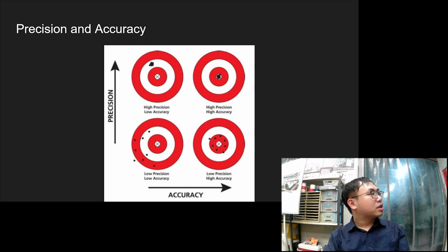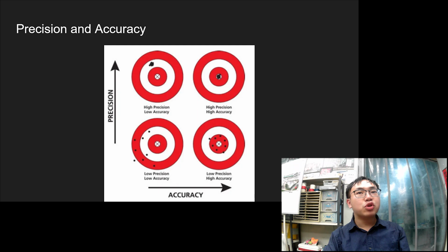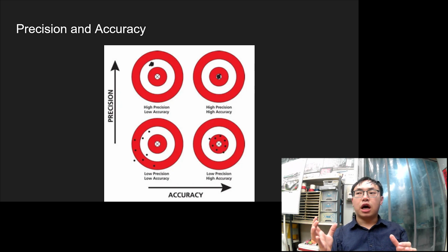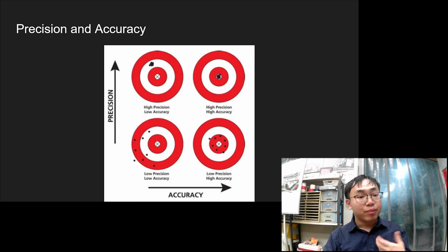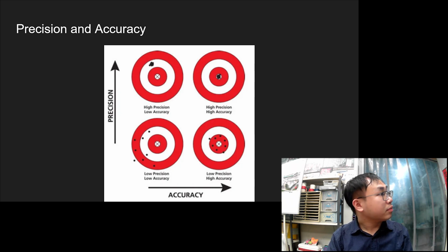So this is about the precision, and about accuracy. You see these two diagrams. The accuracy means how close you are to your target. So sometimes you may have a very high precision, but it is not accurate. So it will look like this. That's why we always have to recalibrate our measuring equipment from time to time. When time passes, the accuracy may decrease. So we have to calibrate our equipment so that the accuracy will increase.